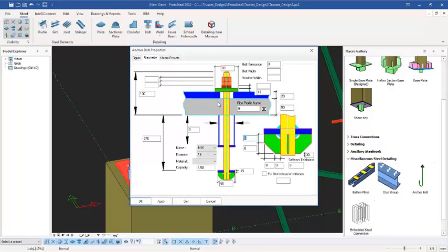You come to the geometry, and then you can see we have over here 60 for the bigger washer. We wouldn't want this bigger washer, but we want the smaller washer right there. So in these provisions we key in 0 right there. The name is M16, so we consider it M20 because the diameter is 20. All right, the hole diameter is 20, and then we have tolerance of 2, which makes up 22 millimeters.